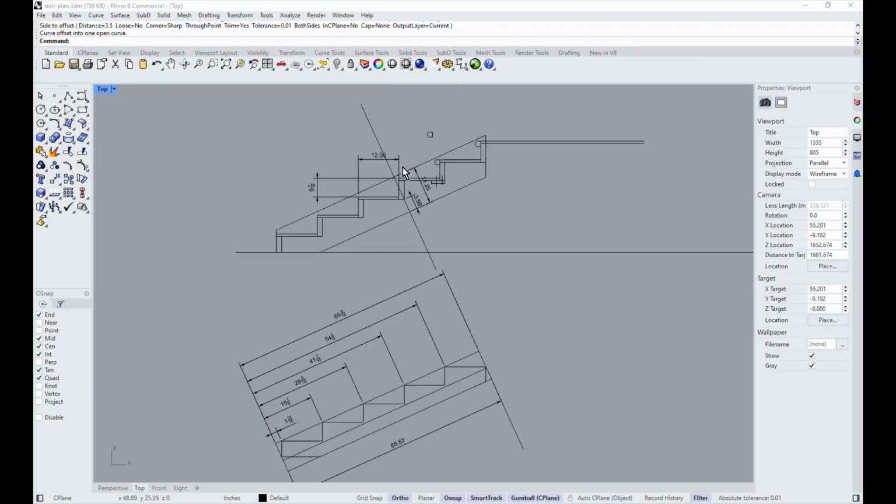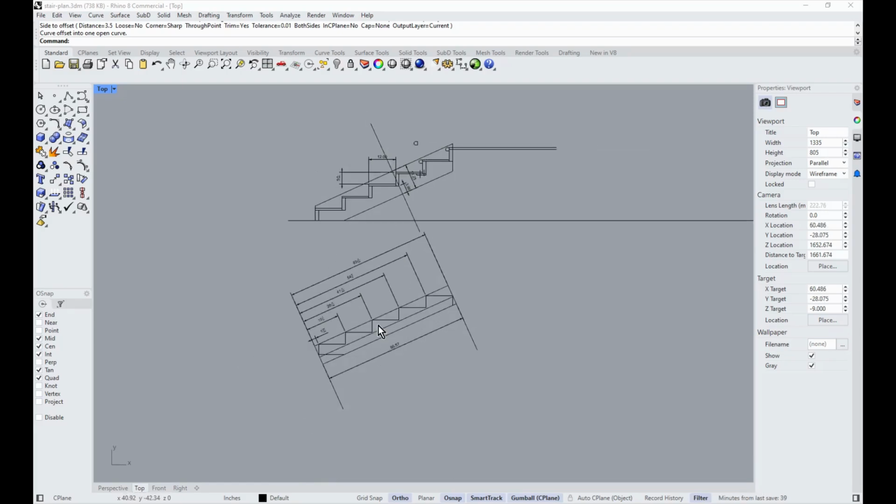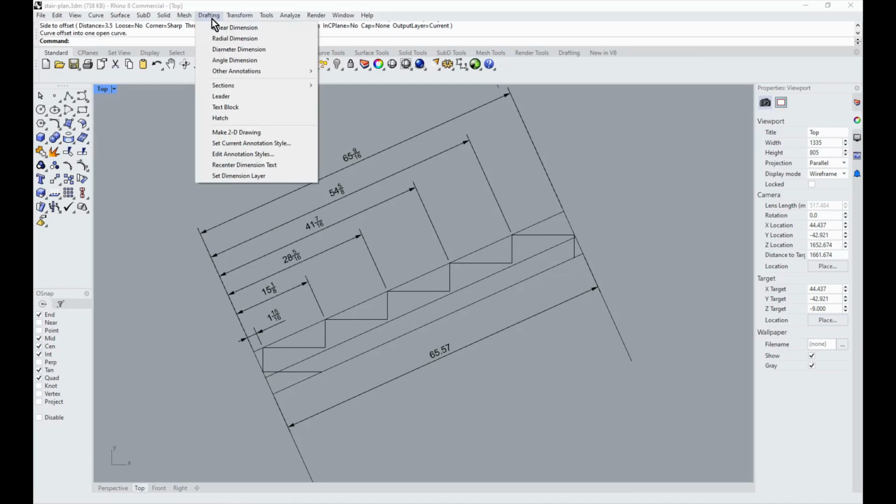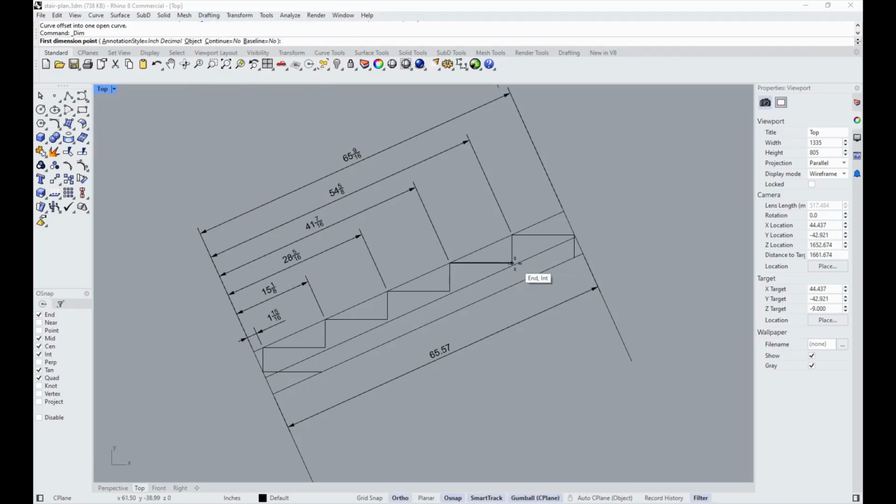But if you can have real dimensions in front of your face on any kind of CAD system, it's so much easier. If you don't have that, and you've got a big piece of drywall, maybe the staircase is going in after drywall's up, or even on the concrete floor, lay it out at 1:1 scale, and especially watch out for that last little bit like I showed you before, because that's where a lot of this failure happens.